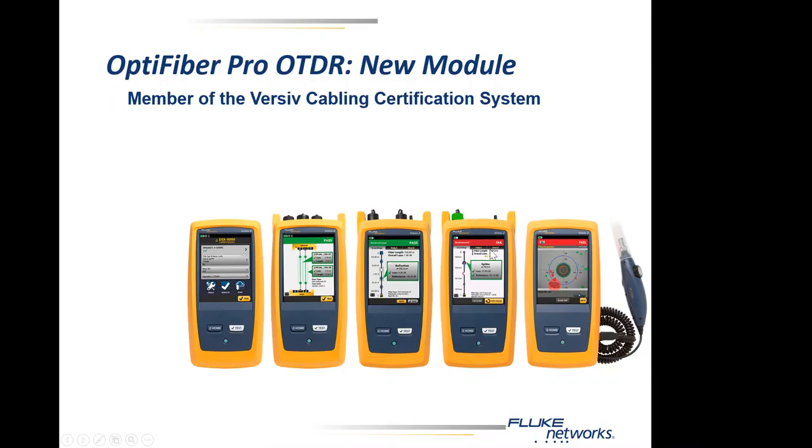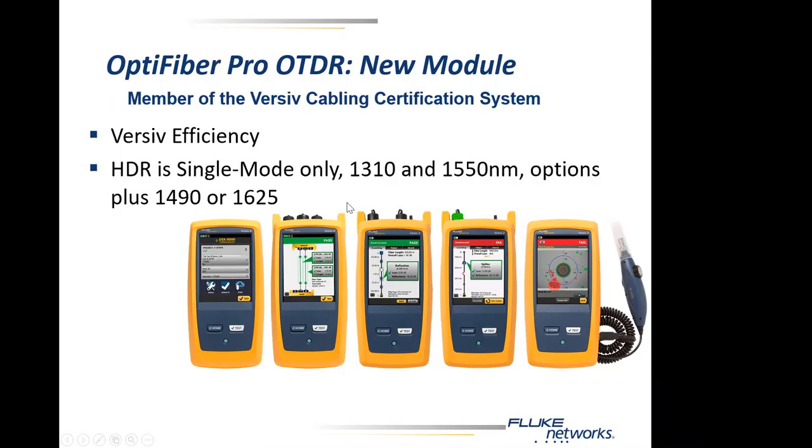So this is the HDR OTDR, but obviously we have units for other environments as well. The important thing here being that the HDR high dynamic range unit only operates in single mode, so it only ever has one port on the top, well, one port plus the visible light source, and always operates at 1310 and 1550 nanometers, and then there are optional 1490 or 1625 nanometer outputs as well. And you can opt to have just the two or either of the three, 1490 or 1625 outputs at the same time.